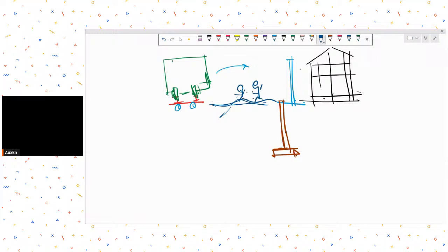People are standing. So you go with a retaining wall over here. All right. And what you can do is, in between your plinth and retaining wall, you try to conceal this space and fill it up with some damping material like sand, let's say. Okay. So all around this building, you create a moat. Moat means a partition, and try to fill that partition maybe with some damp proof material like sand, and that can act as a good vibration control mechanism for you.